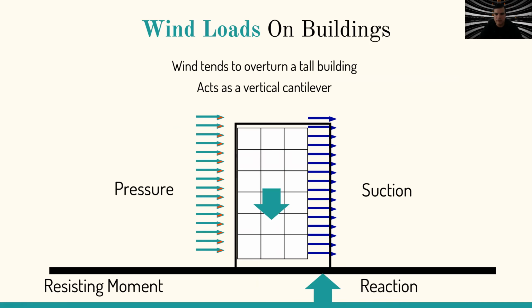As I was telling you, it's very important to take wind loads into consideration, especially in tall buildings, because they can overturn the building very easily. When engineers calculate a skyscraper, the weight of all the material, that is dead load, and the weight of all the live loads for furniture and people is not the most important. What is dangerous in a very tall building is the wind.